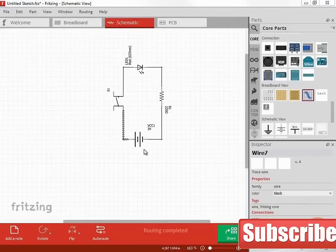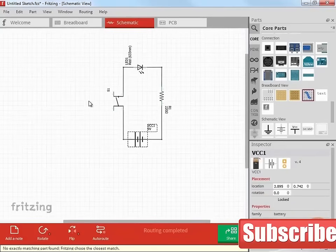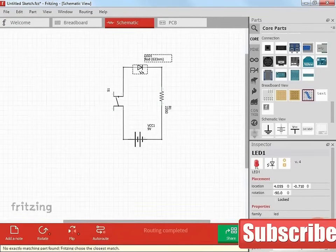We'd like to use a 9-volt battery, and the library defaults to a 3-volt battery, so we'll go to the properties for that. We'll select our 9-volt battery. Our switch is either through-hole, THT, or SMD, which is surface mount. We'll leave it at THT, which is through-hole. Our diode, we can leave it as 5mm through-hole, or, let's just for fun, put it 3mm through-hole.